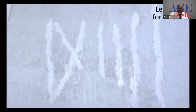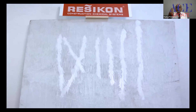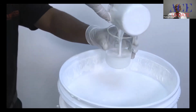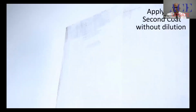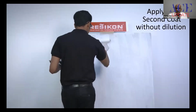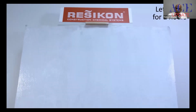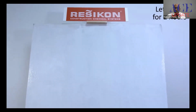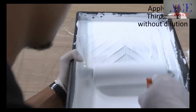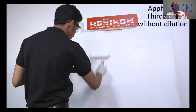So after crack treatment, do the primer application, and after primer application, you have to apply 2 top coats, which you will see now. These 2 top coats you have to apply undiluted. You don't have to dilute with water. These are ready to use. You can apply it by brush or roller, both. The gap between each coat should be around 4 to 6 hours.